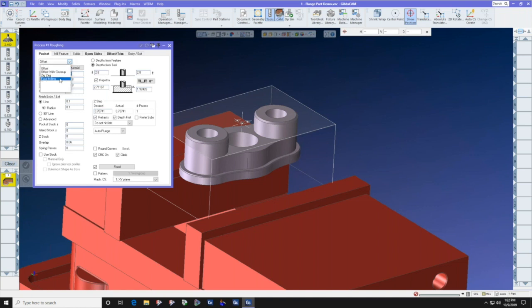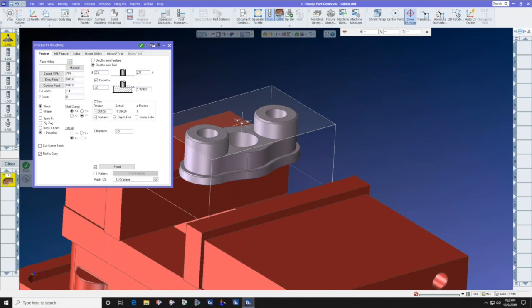We're going to select face milling, and we're going to start at 20 thousandths and finish at 0. Our entry and exit clearance planes are 0.1 and 0.1. We're going to machine stock, one direction for best flatness. We're going to start in the X plus Y minus corner so that we throw the chips towards the back of the machine and put the force of the cut towards the hard jaw of the vise.